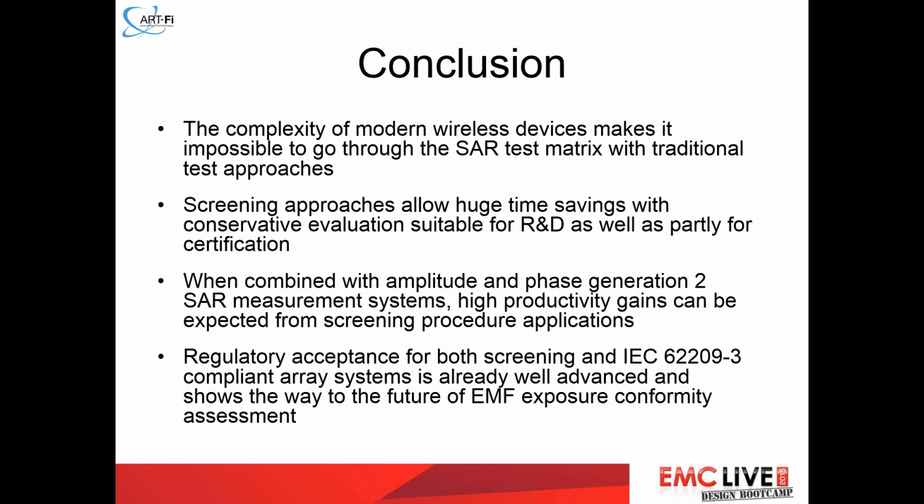If we say we're measuring a WCDMA signal and the spectral content doesn't look like it, the system will know. Also, when the system is used for automating the base station simulator, it ensures that the SAR measurement system is synchronized with the parameters entered to the base station. In this way, you avoid measuring while the transmitter is emitting in a different mode.